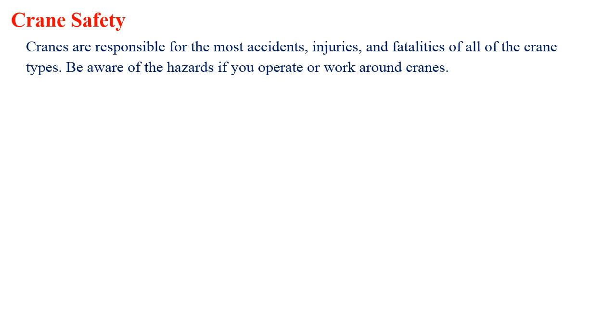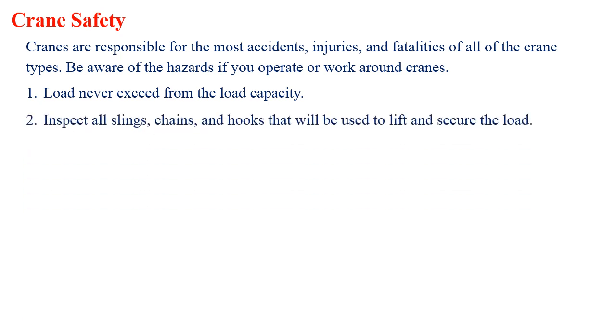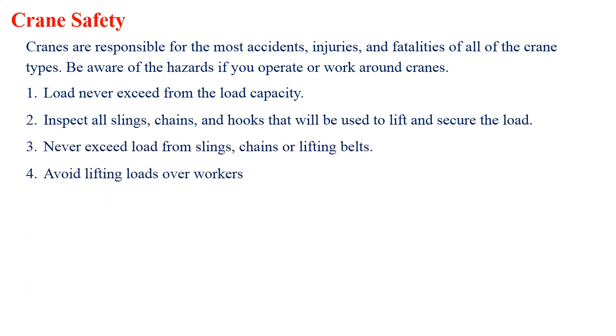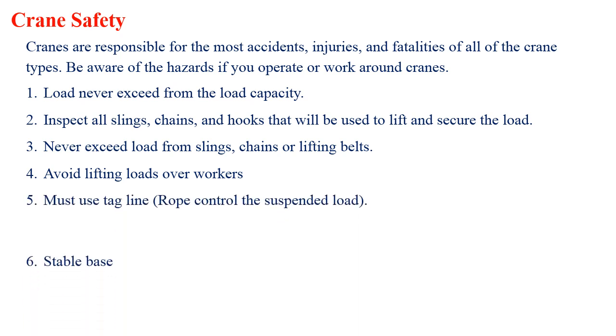So here are some crane safety tips. Cranes are responsible for the most accidents, injuries and fatalities of all the crane types. Be aware of the hazards if you operate or work around cranes. Number 1. Load never exceeds the load capacity. Inspect all slings, chains and hooks that will be used to lift and secure the load. Never exceed load from slings, chains or lifting belts. Avoid lifting loads over workers. Must use tagline rope to control the suspended load.